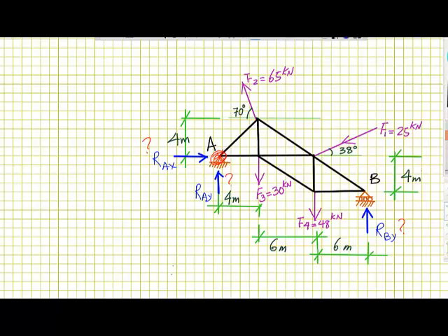As you know, we have to resolve the inclined forces to x and y direction and make sure that we have the perpendicular distances to the point of rotation. Let's start with F1, which will be resolved into its x component. In my sketch, I'm showing the line not exactly on top of the truss, because I just want to show you that this will be resolved into two components, component x and component y, but normally these lines align with the same element of the truss.